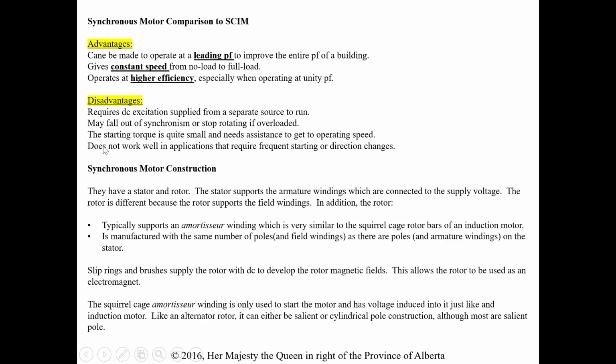The starting torque is quite small, again, so we don't want to start it under load, and starting and stopping or changing directions is not good either. That all goes back to the fact that they're not good at starting on their own and they need help to get going.